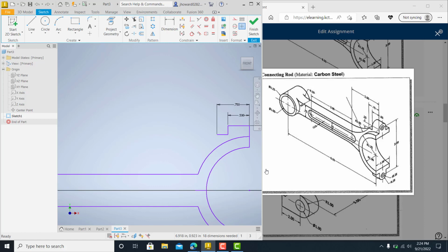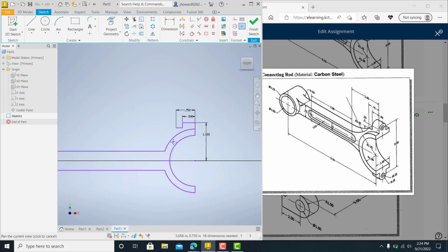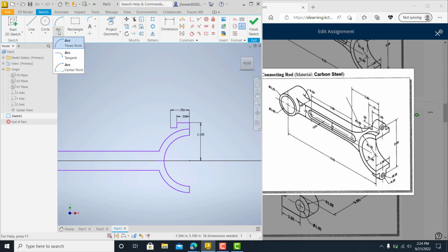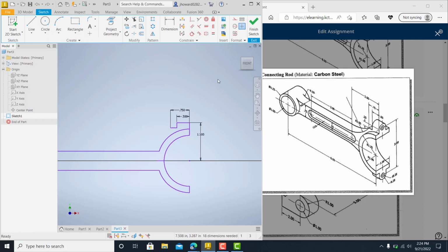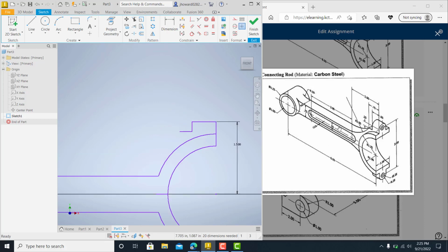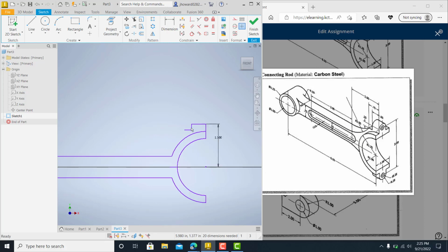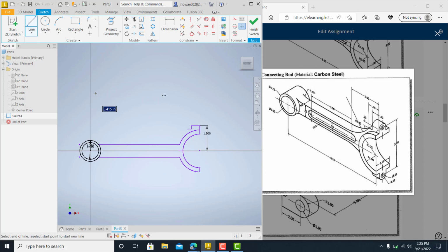where the center point of that is. I want to show you guys a trick on here. Now, there's ways of doing this. You could go in here and use a circle and use your constraints and things like that. I want to show you all a drafting technique. And what it is, I need to offset off this line right here 2 inches. So I want to bring a line up. Hit my dimension from this is going to be 2 inches, because that is what this radius is.